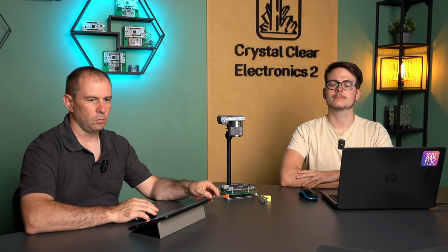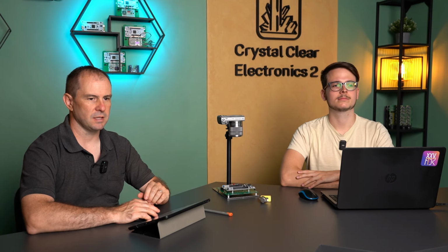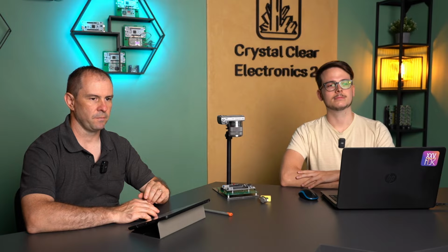In our embedded systems for complex tasks, we often use some kind of embedded operating system to schedule tasks. However, real-time operation of the operating system cannot be ensured without accurate timing. In most cases, the operating system running on microcontrollers uses a dedicated counter and timer module, the SysTick Timer, to perform scheduling tasks. This timer is found in almost all Cortex-M based microcontrollers, which are developed specifically for embedded systems.